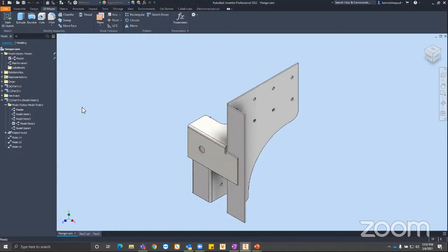What I tend to find is that people use level of detail to remove parts or pieces from the screen, like, hey, we're going to take this out of the bill of material for a given instance, but it really functions off of suppressing components, which has its own dangers. Most of the time, you should be using design views to control what I'm seeing at certain areas.